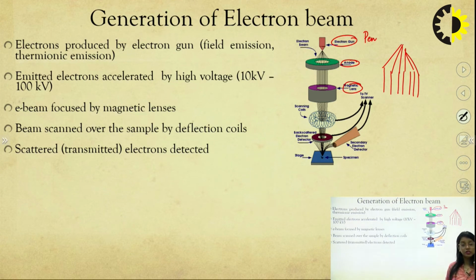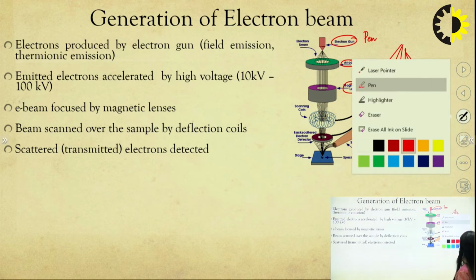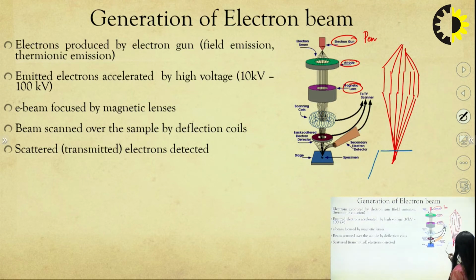We can understand that the precision level of the electron beam is less than 0.1 microns. So this magnetic lens is further converging it. We can see that this magnetic lens is further converging, so that when we have a base at the bottom, we are very much pinpointed that we want the lithography to take place only at site A.